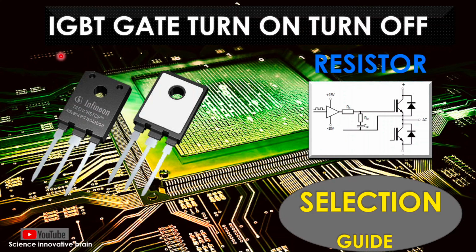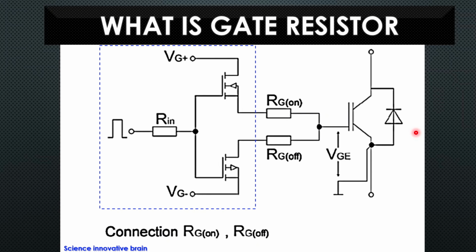So guys, welcome to the IGBT gate turn on turn off resistor selection guide. Here we will discuss how we can select this RG value. RG is called the gate turn on turn off resistance, and this is called the gate driver. This is your IGBT. So first we will discuss what the gate resistor is, and before that we will understand why we choose the gate resistor.